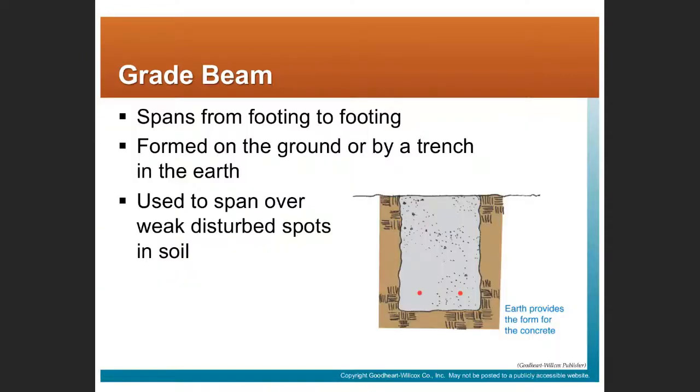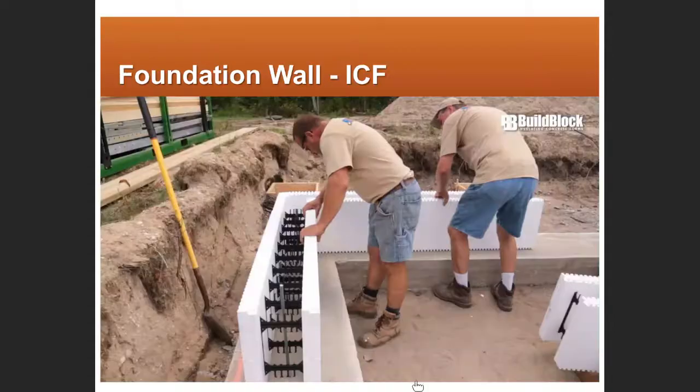So quick question, that ICF would remain in place, it would not be removed once the concrete is set? Yes, that is a good question, Nicole. Yes, the ICF remains in place. So this is different than a typical form, right? Typical formwork, you build the formwork, you put in the rebar, you pour the concrete, and then you take down or strike the forms when the concrete has set up a little bit. In this case, the insulation stays.